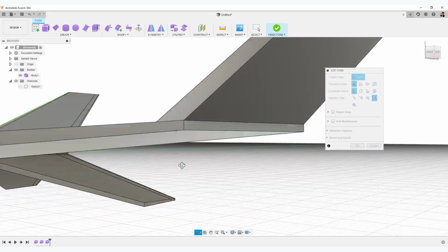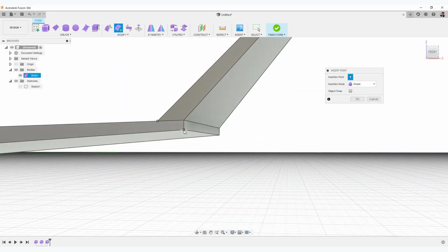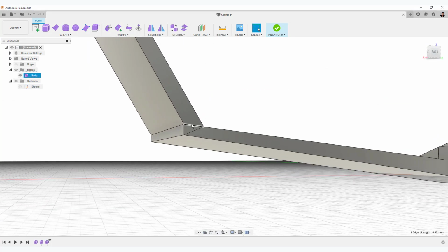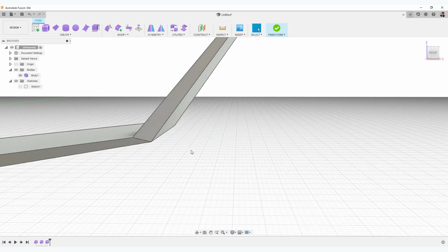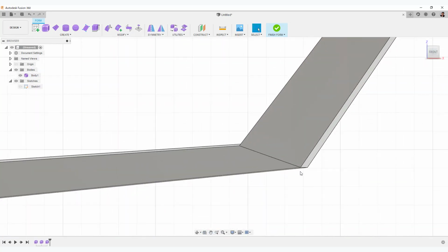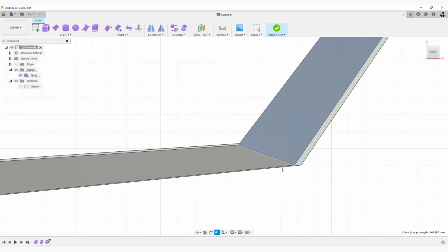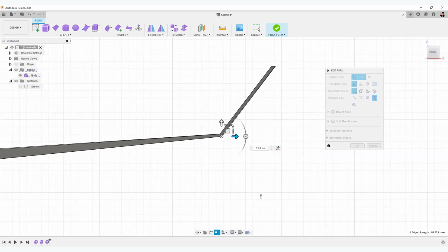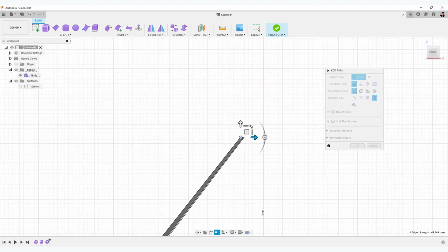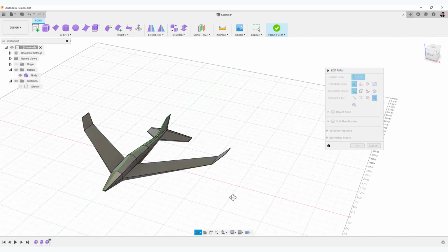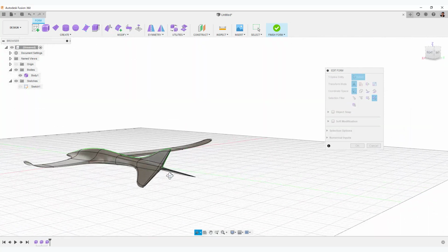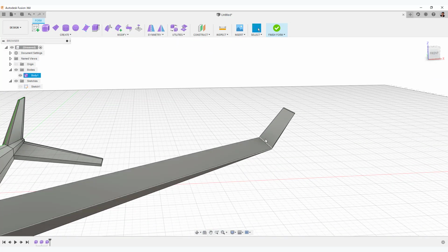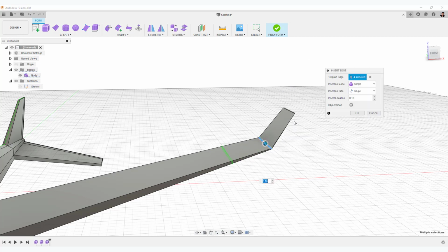Remake the construction. Create edges like this. And delete this edge. Switch to the front view to adjust the change in width of the face to the same. Adjust the angle R. Select an edge to insert an edge.